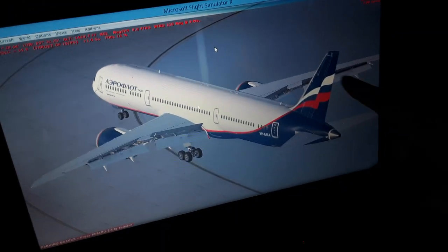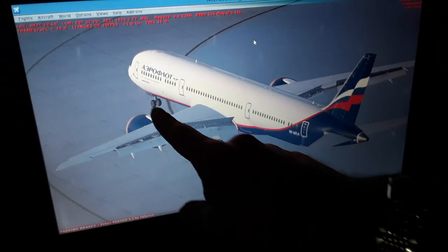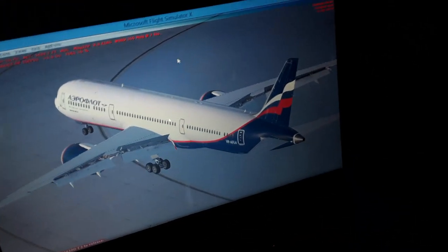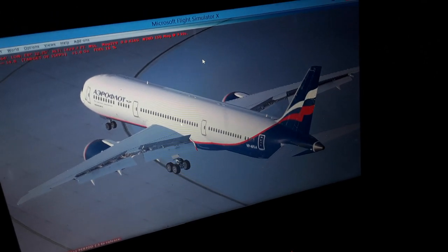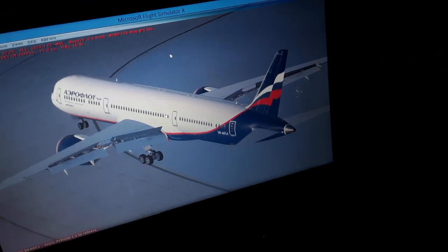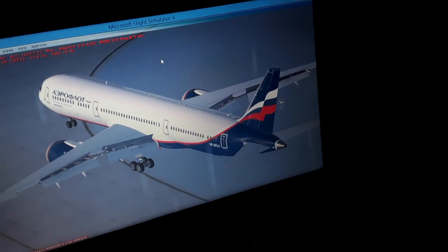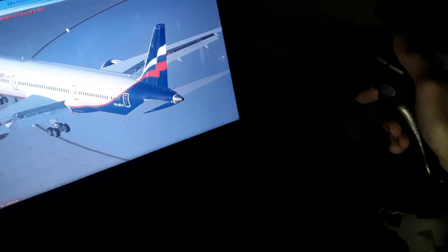It is the inverse when you land. You have first the rudder aerodynamically effective, then the nose wheel will come in as you slow down your airspeed. So when you take off, the nose wheel control decreases, and then deactivates from the computer. Then you have only the rudder, and now the inverse is happening in the landing process.